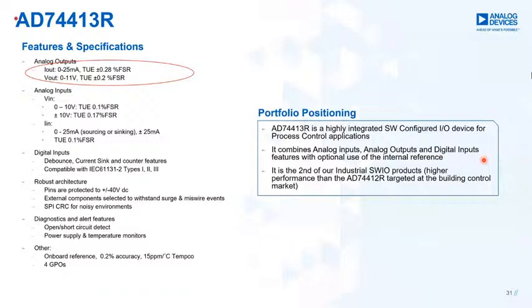And in case of inputs, it offers 0.1% accuracy for the voltage input, and 0.17% for the bipolar input, and for the current inputs it's about 0.1%. These figures are without calibration, please note that. And the digital input scheme is compatible with IEC 61131-2, and it addresses all types 1, 2, and 3.